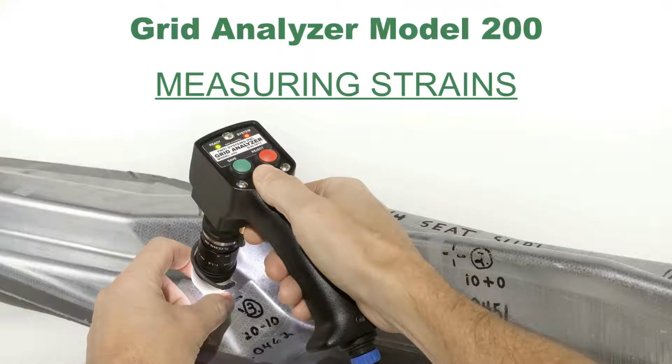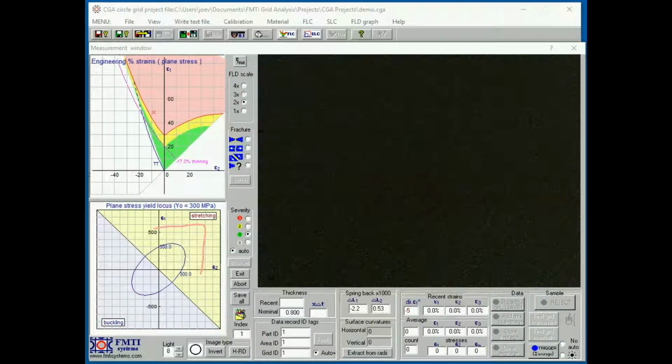My name is Joe Verhaeg, General Manager, and we'll be showing you how to use our grid analyzer to take fast, accurate strain measurements. All grid measurements are taken from the measurement window. The flashing red cross and the flashing LED on the analyzer indicate that the software is ready to take a measurement. The green arrow at the top left indicates the rolling direction.